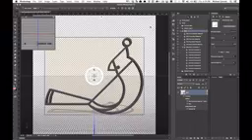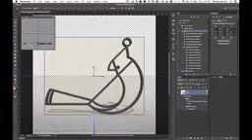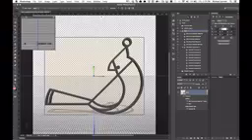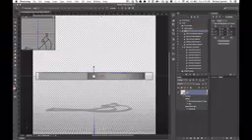degrees around the x-axis so that it sits flat on its side. To do this, click on the last icon in the Properties panel. This will give you options for changing the object's coordinates. We want to rotate this object 90 degrees around the x-axis, so enter the value 90 into the x-axis rotation field. This is the top option in the center column.